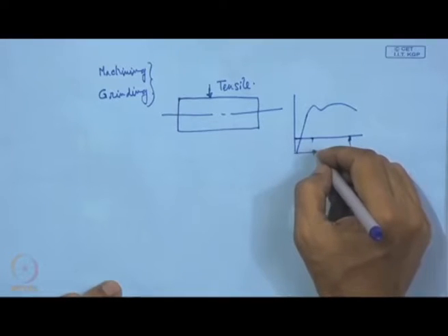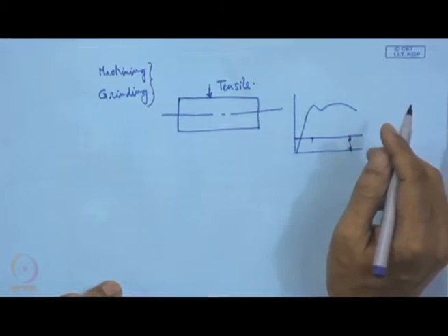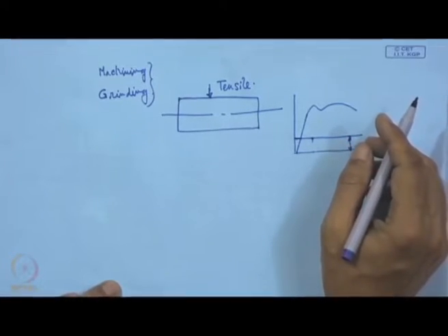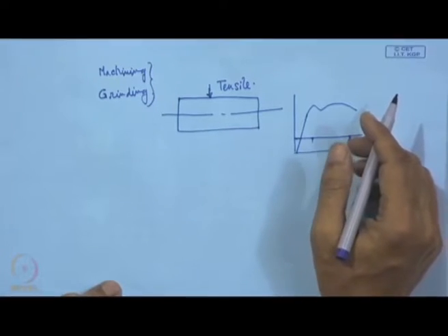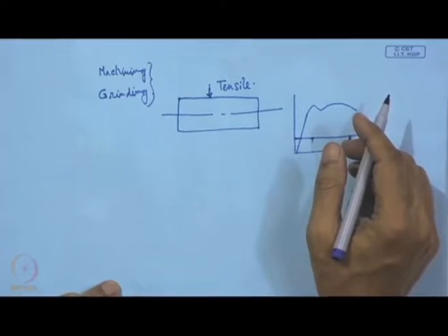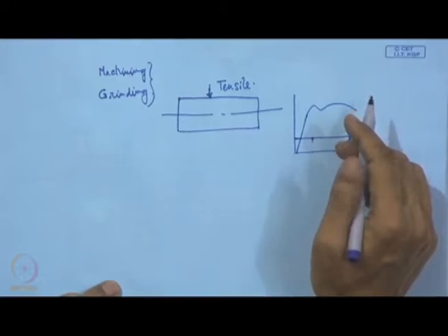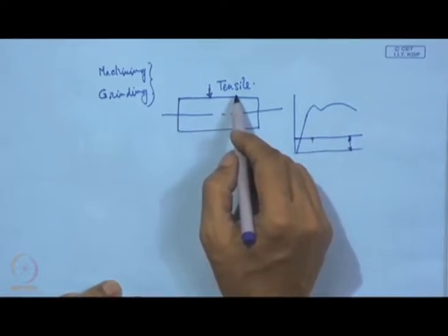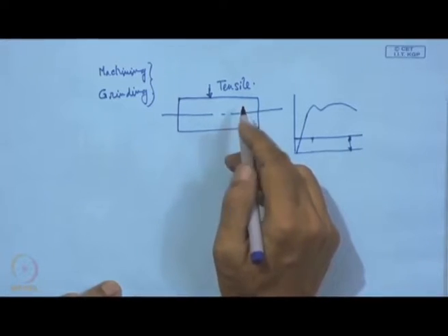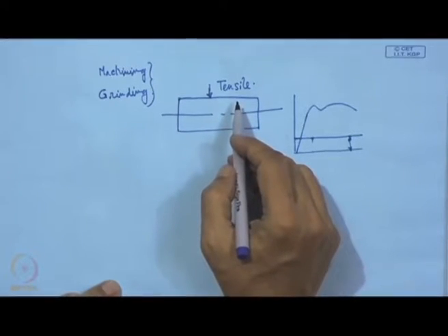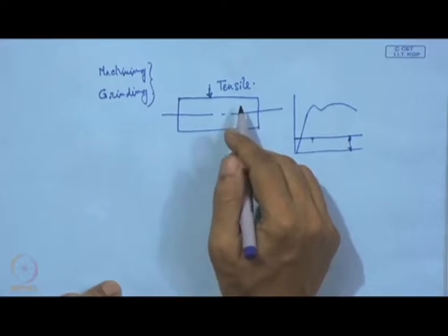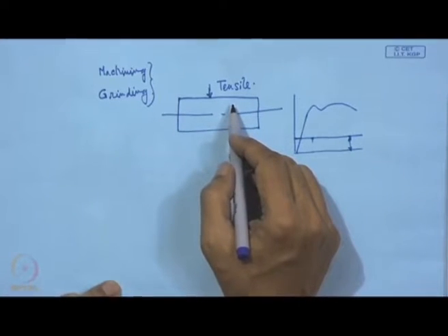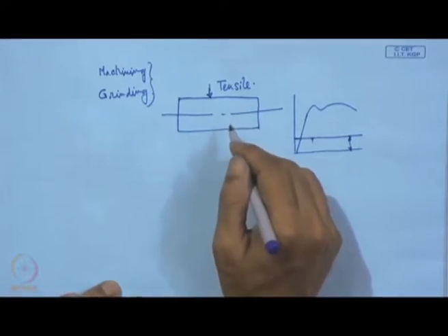So, this is a loss of strength of the material. Now, it is our objective to conserve the strength of the material. That is why there must be some process of neutralizing the tensile stress and also inducing some compressive stress. So, this is number 1, how we can do it.